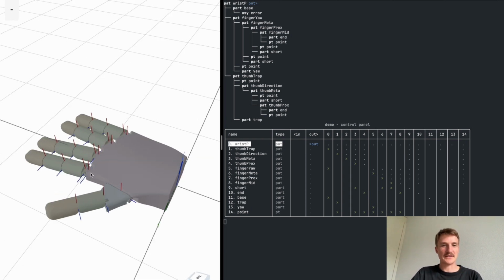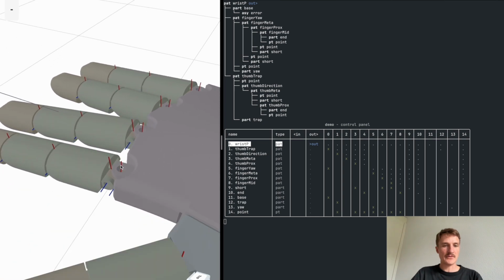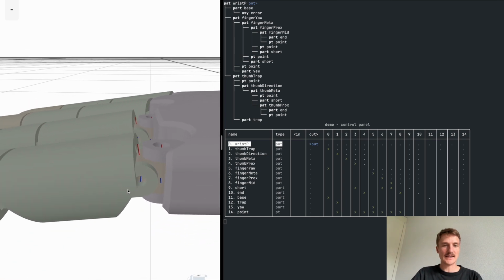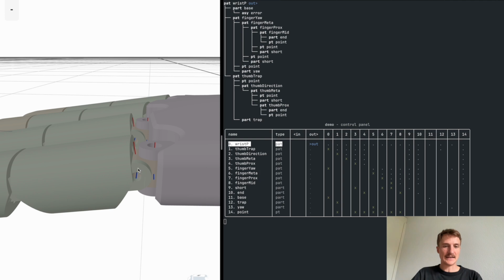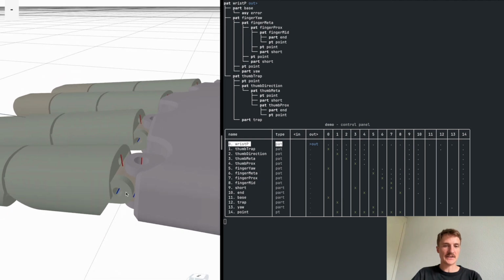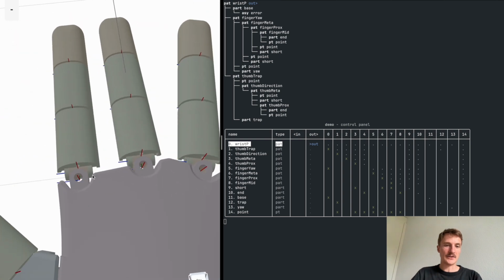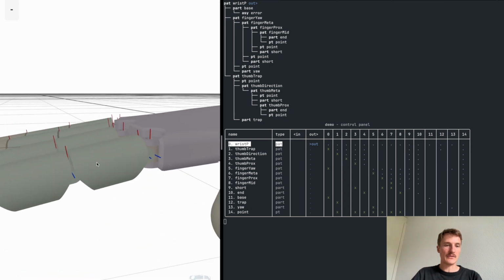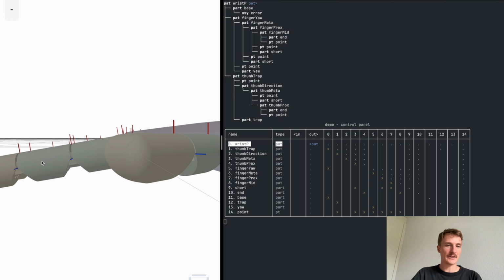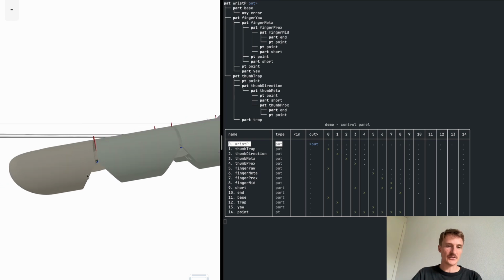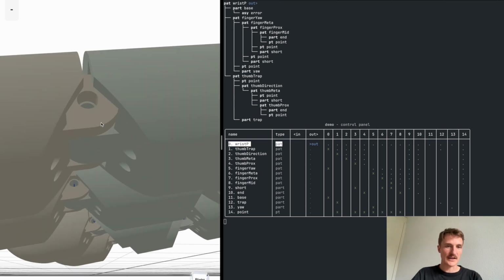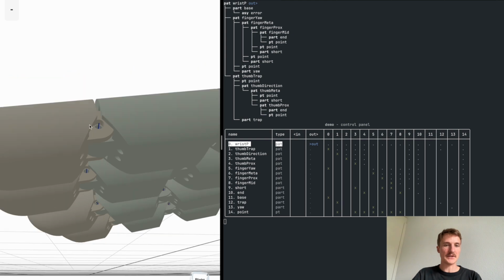So for the purpose of this demo, let's try to see if we can automatically add ball bearings at every finger intersection here. So this means we want one on that side, one on the other side, and we want this for every single finger interface to the next section. As you can see, we currently don't have any bearings there.